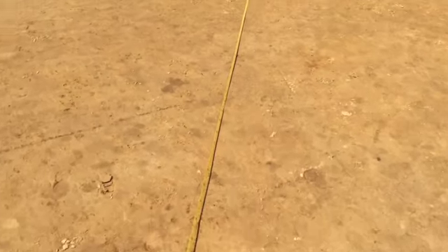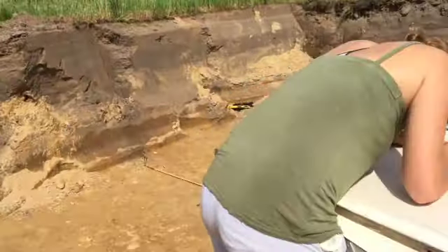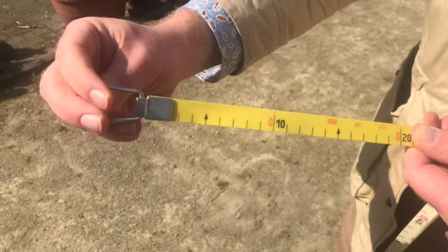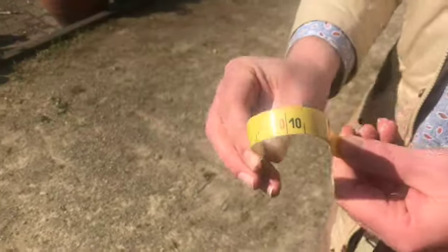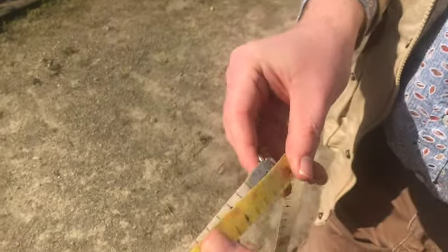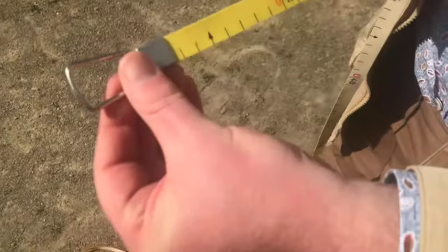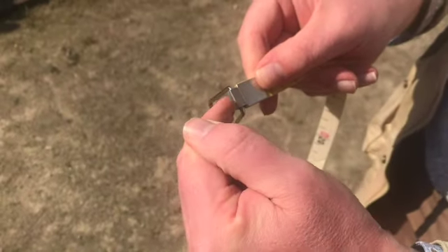In between 2 grid points we fasten a measuring tape with surveyor arrows. The position of the 0 end of a measuring tape depends on the kind of tape. In this case, the 0 end is the flat piece of metal of the end strap. You can always check the position of the 0 end by folding the tape.